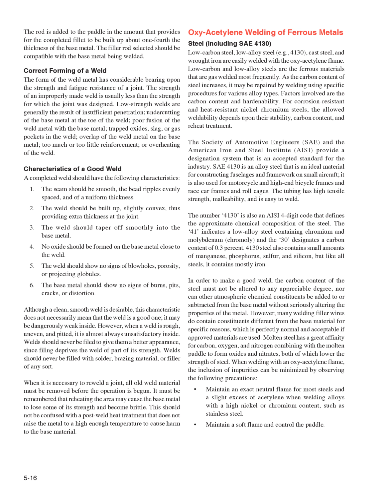4. No oxide should be formed on the base metal close to the weld. 5. The weld should show no signs of blowholes, porosity, or projecting globules. 6. The base metal should show no signs of burns, pits, cracks, or distortion.